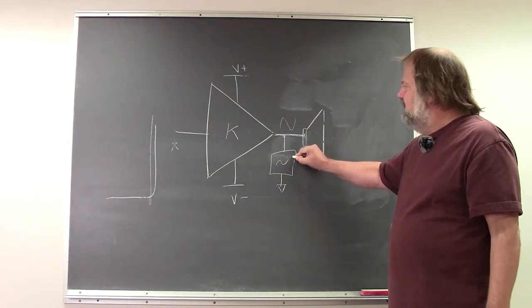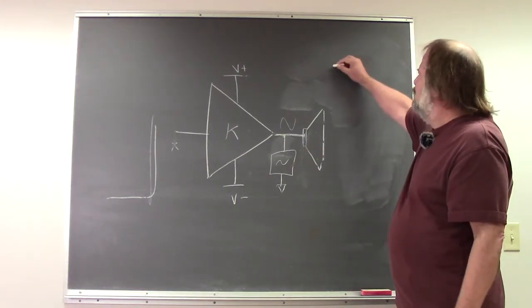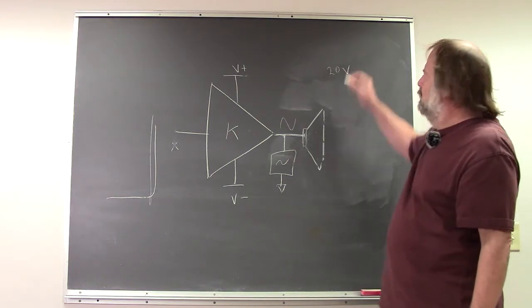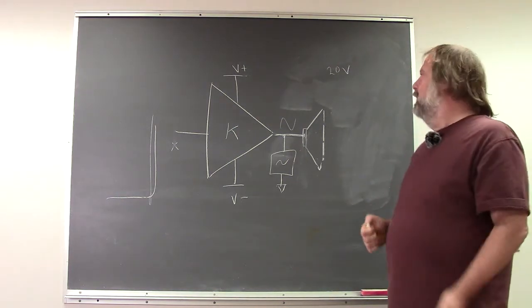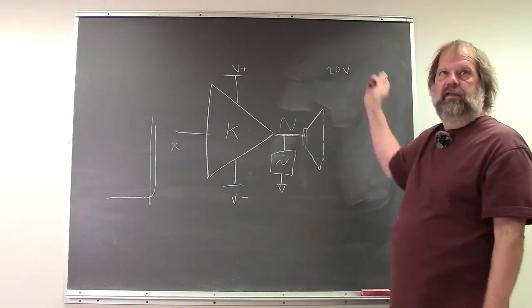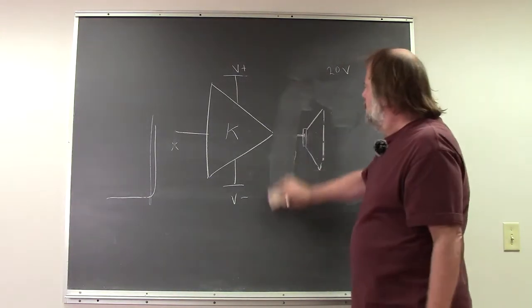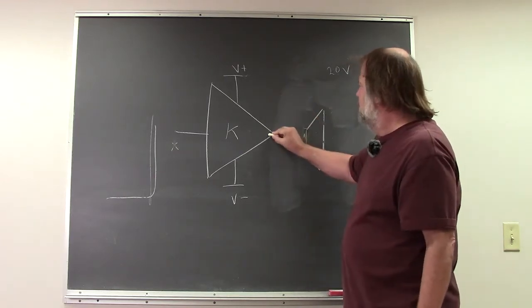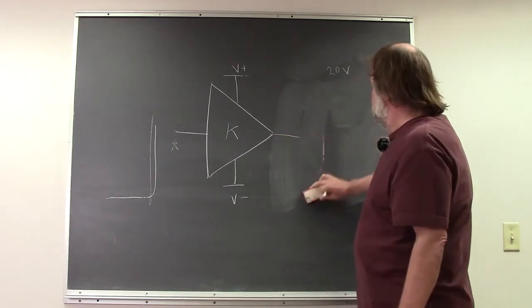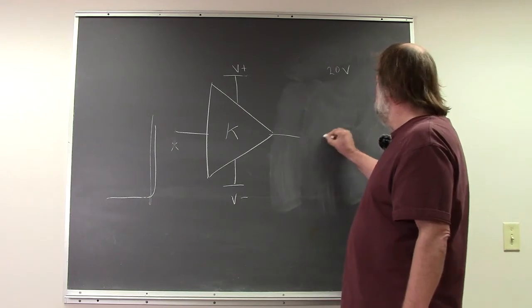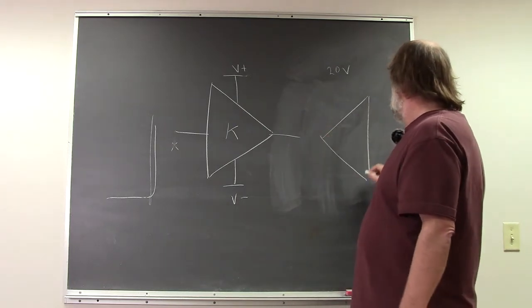And that's a very, very easy way, because if you notice it gets really loud and it never swings more than 20 volts, well, there's half your answer. Because now you know roughly how big the amplifier has to be just from that. So, the second thing, how do you get more voltage? How do you get bigger amps? Well, one way that's common is through bridging.